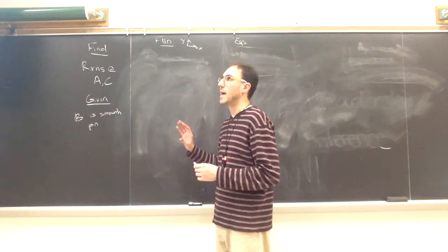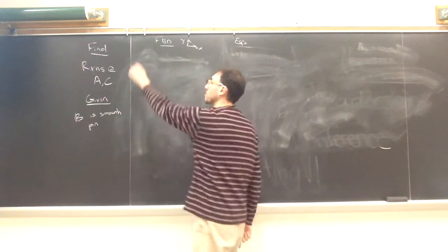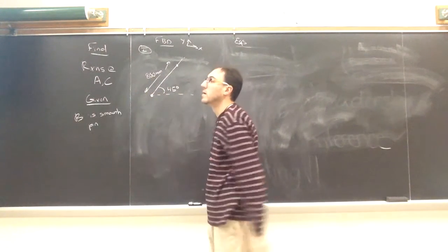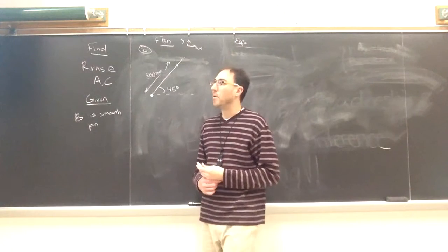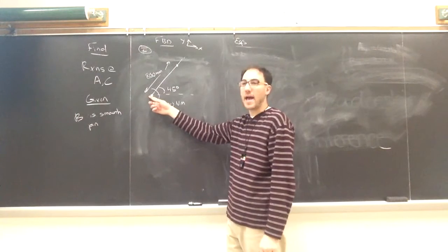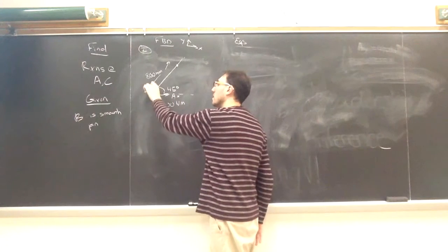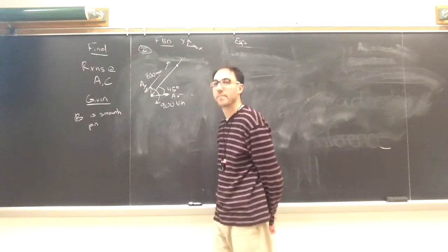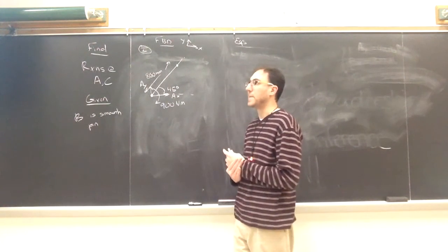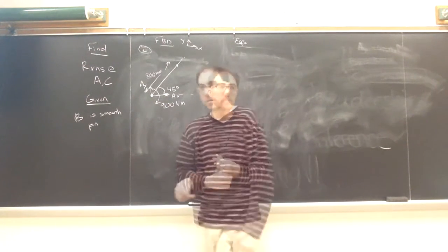So for our free body diagram step, I'm going to break it into its individual components and draw their pictures. I'll start by drawing AB. We have one couple acting on it, 900 Newton meters. At A, we have that external support. We have a pin, which we can model as an AX and an AY. And what do we have happening at B, where it's connected by that peg and slot to member BC?